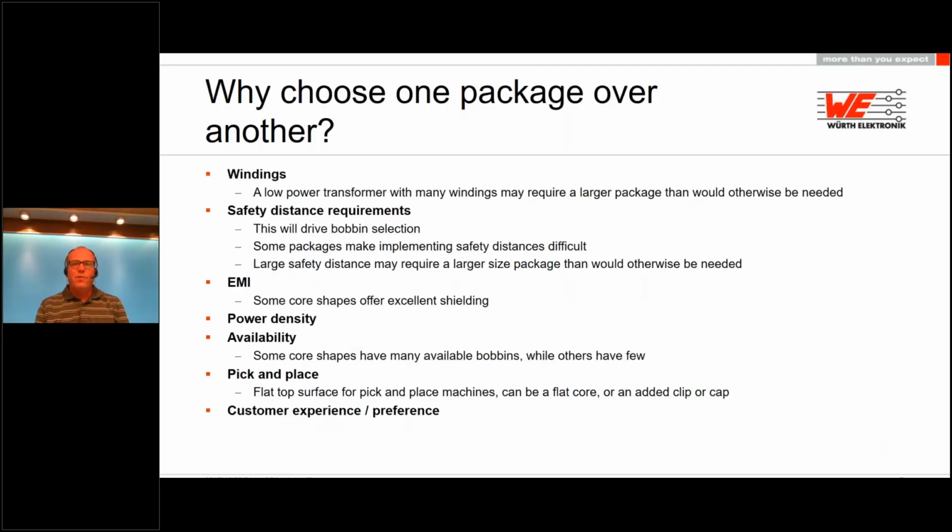So here's a few other details why you may choose a particular package. Criteria like low EMI, the need to run it through pick and place, or a safety standard would affect package selection. So, in a bit, we'll go through several common packages one at a time and discuss how they relate in each of these categories.